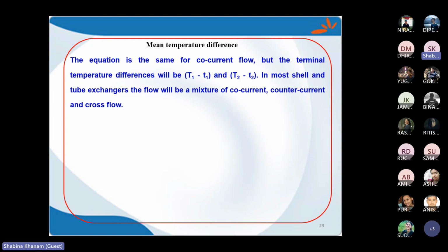Further, in the shell side, fluid will enter from one nozzle and cross some of the tubes. Because a baffle is there, the shell fluid will not directly move from left to right or right to left, but it will move from top to bottom first.